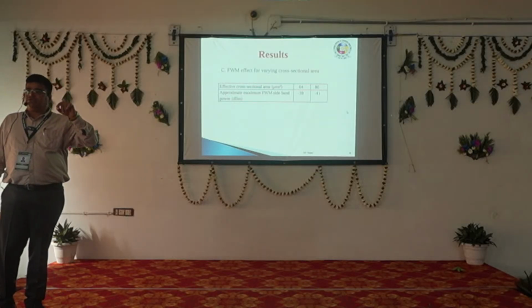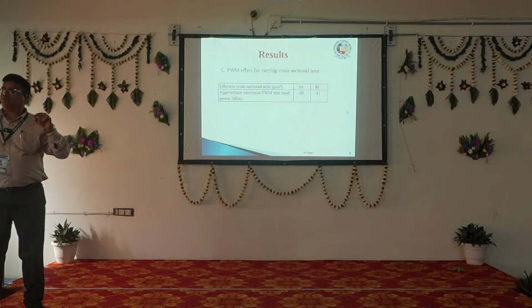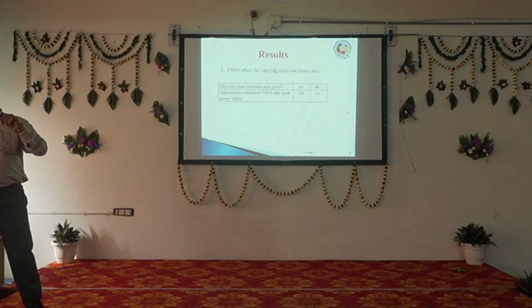Again attenuation. Attenuation is very high. The single mode fiber attenuation is 0.2 dB per kilometer, basically what is available till now, the well refined fiber. Clear? But if you go for multi-mode fiber, 0.2 dB will increase to 0.5 dB. If the attenuation is very high, again you have to go for multiple number of amplifiers, multiple number of repeaters.